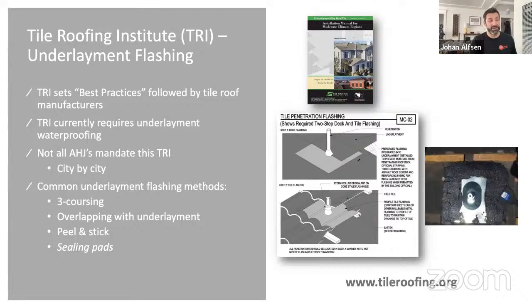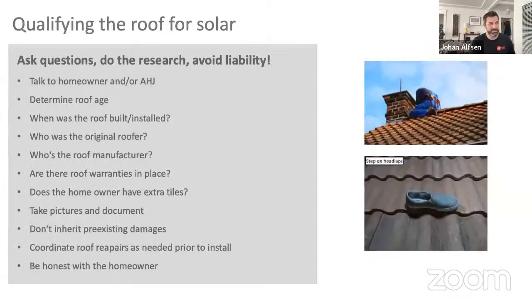But most installers take the least path of resistance and install mounts, put sealant over the bolts, and then cover the tile and put a flashing over it on the top. Some will argue that underneath the tile is not going to get as much water directly onto the penetration, and the sealant is enough. So it's an ongoing debate, and I'll talk about that as we get into some of these systems or these products that we've released.